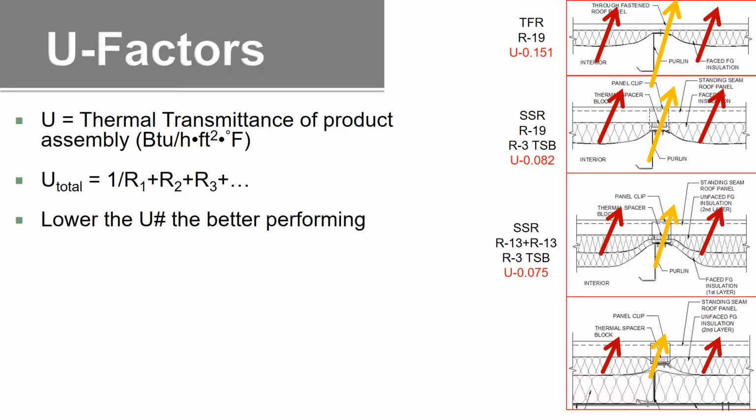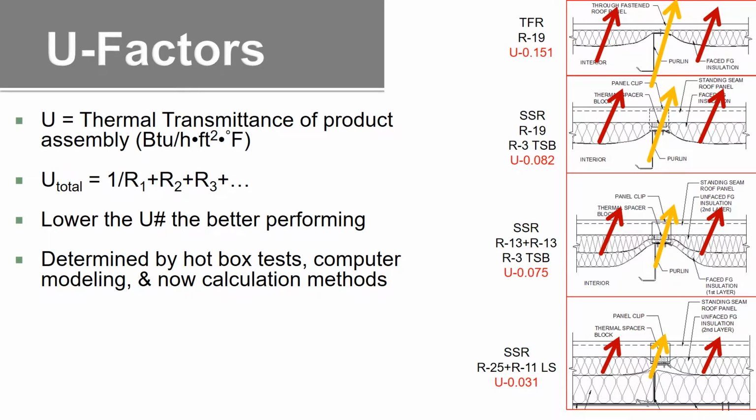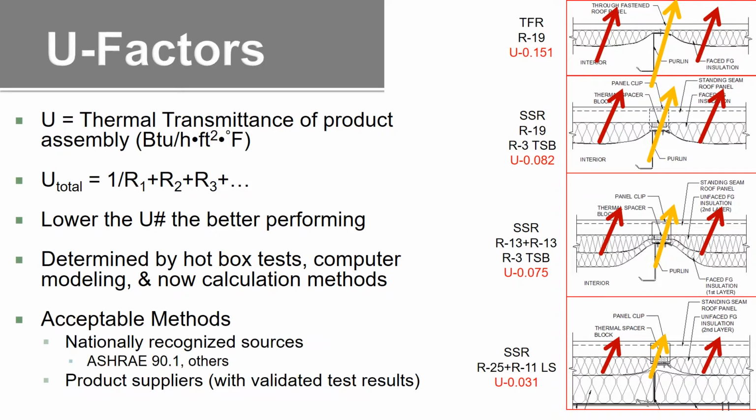Today's energy code fills the cavity. Obviously a lot less heat loss because this whole area is being surrounded by insulation. And so you've got 2 layers, a lot going on here, so that means more thermally efficient. The lower the U-factor number, the better the performing.